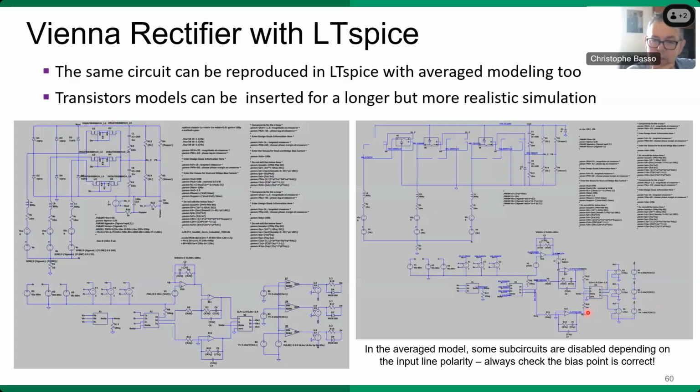I took inspiration from the Microchip application notes that I referred to before by building an extra loop here, observing the voltage across the two output capacitors. It's a low frequency loop, low gain loop. Then you can control the zero input here of this inverse modulator to balance the voltages between the two capacitors. And I've run the example in LTspice and it worked fairly well.